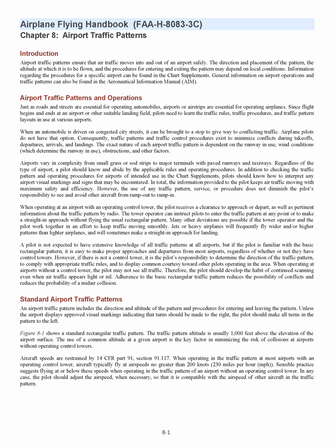Chapter 8, Airport Traffic Patterns Introduction. Airport traffic patterns ensure that air traffic moves into and out of an airport safely. The direction and placement of the pattern, the altitude at which it is to be flown, and the procedures for entering and exiting the pattern may depend on local conditions. Information regarding the procedures for a specific airport can be found in the chart supplements.